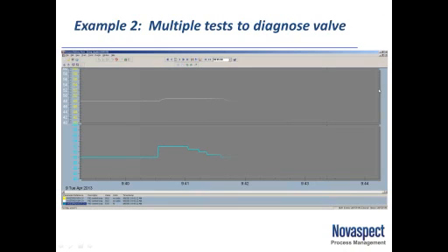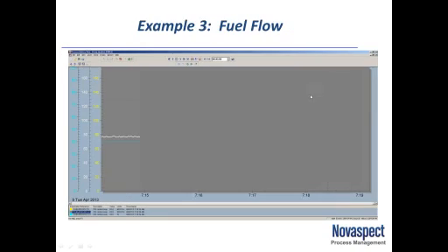All I'm really showing you here, there's no real sample calculations. I was just showing the bump tests that we did to learn about the valve sloppiness. Make sure that after you work out through the sloppiness, you make one additional bump in the same direction to learn the true process gain.